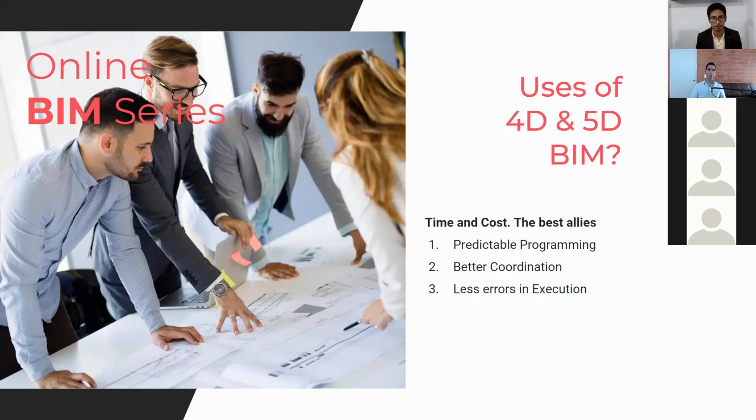And by that, I'm saying that when you combine 4D and 5D, you can get planning, scheduling, and forecasting for the investment and for the construction to be built. In other words, you're planning and doing the schedule on how the building is going to be constructed. You are sorting out the phases. You're establishing the deadlines for any concept of the building to be completed as per the project description, etc. And you have, of course, the cost associated to that project timeline and concept.